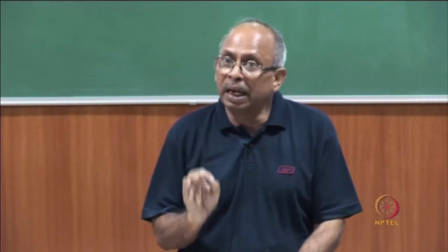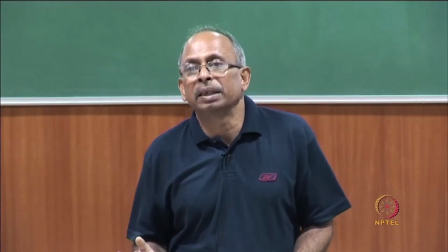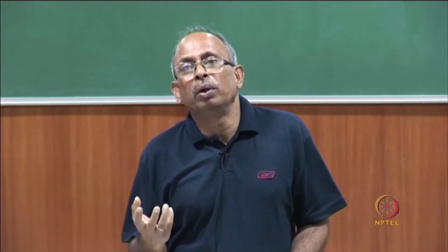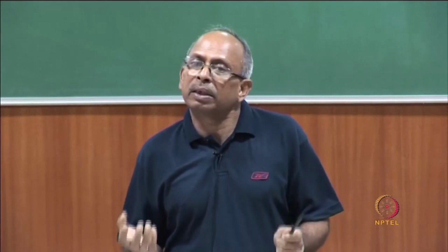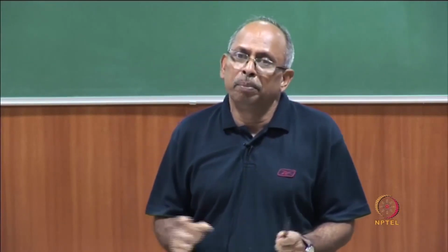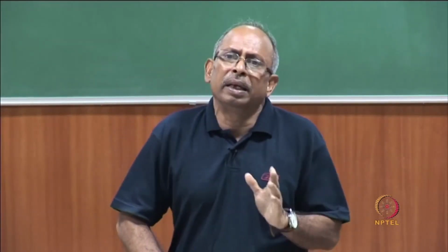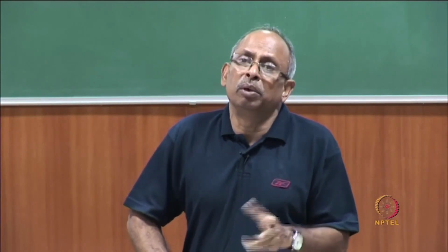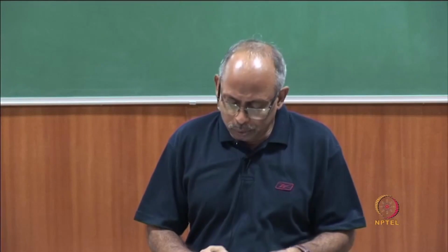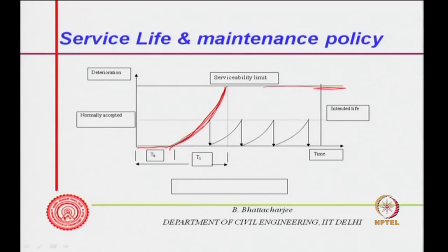Intended design life is that life for which I have designed the structure. I have taken the worst load that can come during the intended design life, and the structure should last during that period, and I prefer that there is no repair or maintenance during that period, because otherwise it will involve cost. But supposing it happens, the deterioration or degradation reaches this limit,